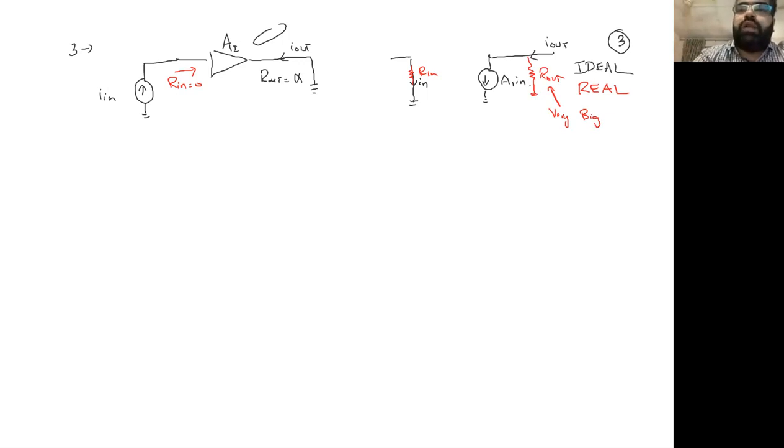And let's talk about the last one, which is the transconductance. Transconductance, all of us are familiar with, where our input is voltage and output is a current. So this configuration, we are seeing almost all of them, but we might not have paid attention or explicitly given the naming, which we are going to give today. And here, what should I write? GM, because again, it's not a unitless quantity. We are talking about I out by V in.